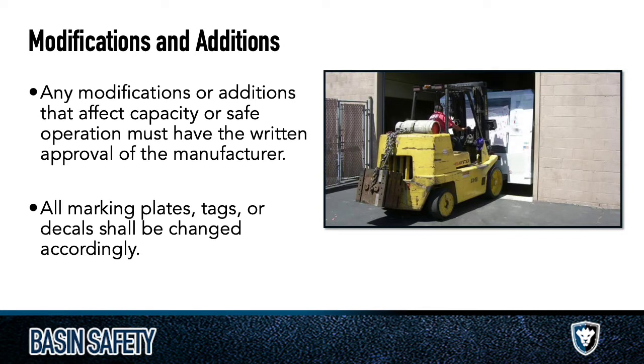So this is true for man lifts and forklifts and cranes. Anything you're using, you cannot install homemade devices on these things without manufacturer's approval. What some people do, and this photo is a great example, is this forklift is not designed to lift the load that it is lifting. So the operator or owner said, you know what, if we put some counterweight on this thing, we've got this handy little hook, we can hook this around the propane support and add this weight to it, and that will keep the back wheels from lifting up when we attempt to lift our load. That's a no-no.